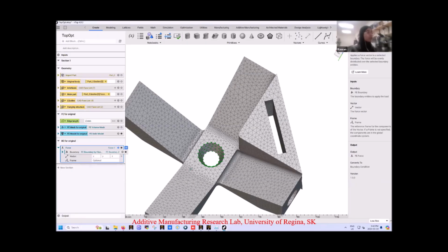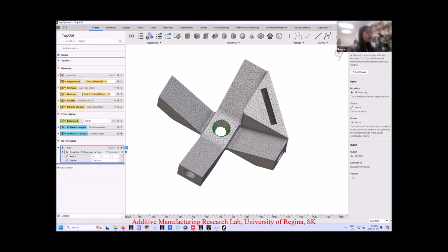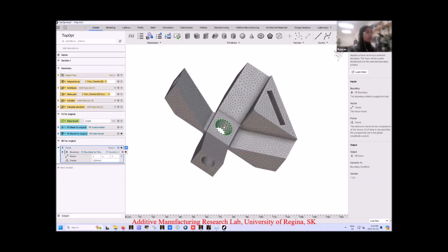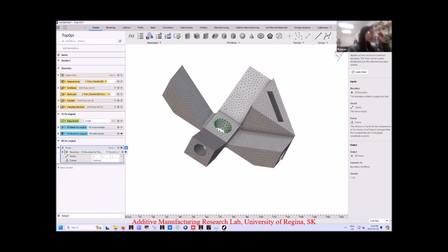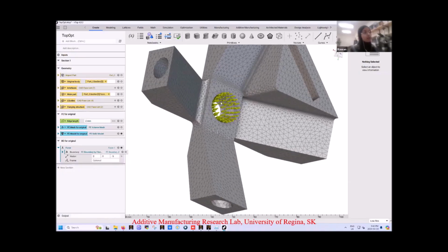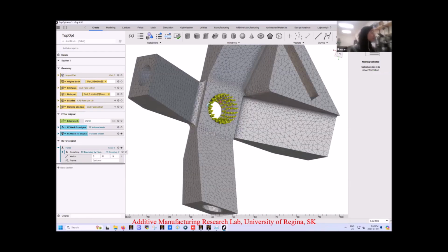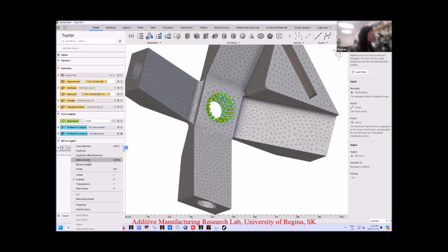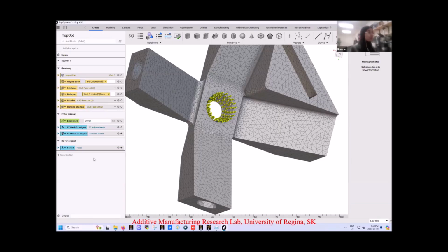And here for your vector, the vector specifies the value of your force. Let's consider that our force is unidirectional, so it's having an effect only at z. That's why we'll keep the x and y 0. But our force will be the gravitational effect and the weight effect of the material put in here. So we'll consider, for example, 5 newtons, and I made it negative because my force is pointing downward. And as you can see here, the yellow glyphs refer to the force. So that's for force number 1. And we'll make it a variable. See, it took the name directly that we specified before.